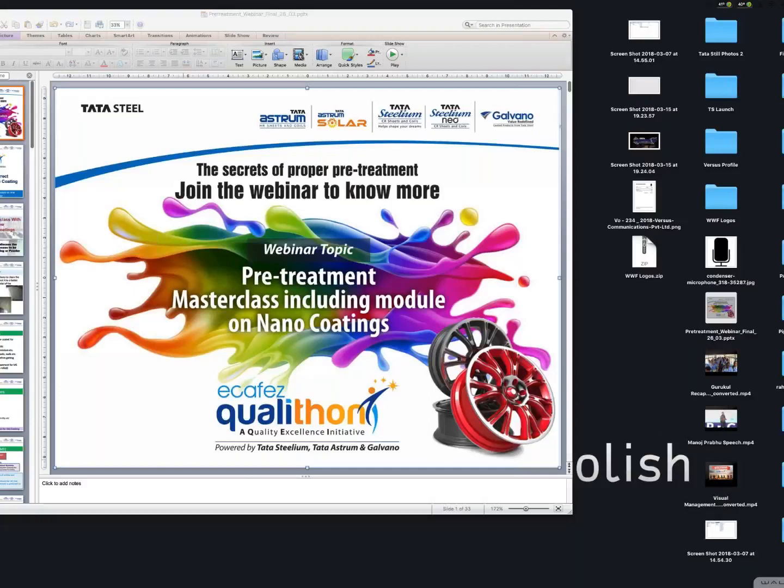Mr. Sridhara KM is asking, if oil is not removed, what type of problems will occur? We will come to that basically. But if the oil is not removed, you will not get a good phosphate coat, number one. And number two, you will not get a good adhesion of either liquid coating or powder coating. The failure will be much faster, and naturally the corrosion resistance also will fail in those areas.